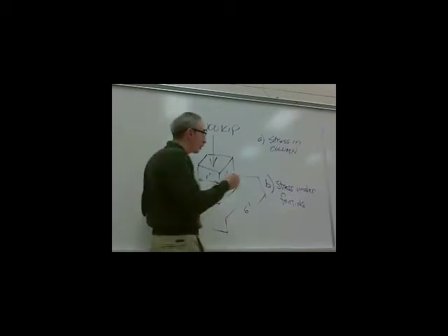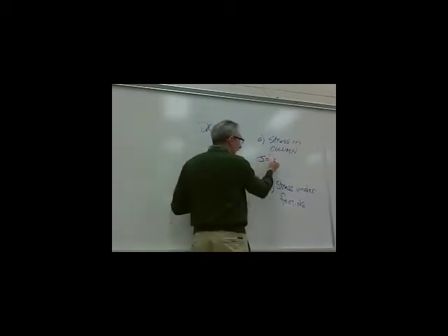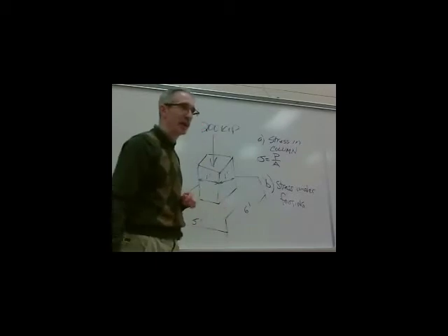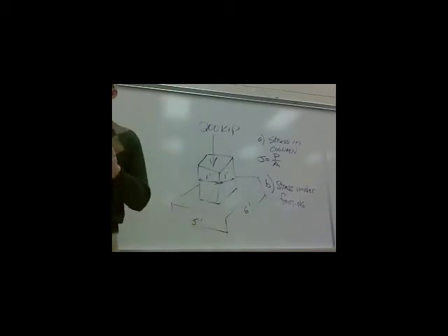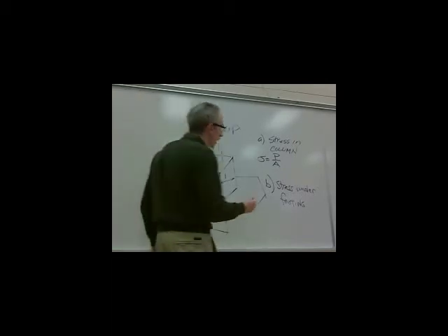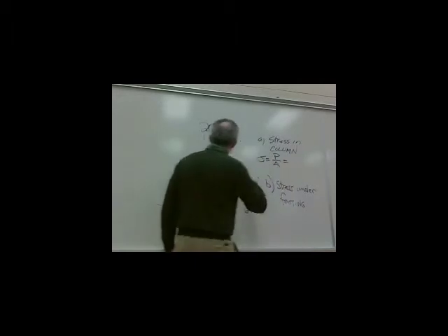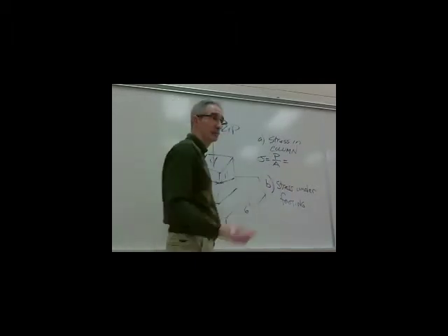So they are both controlled by, again, the formula that we talked about. Stress is equal to force divided by area. You got to think about the area as what is the area resisting that load. So, in the column, you're going to tell me that that's 200 kips.